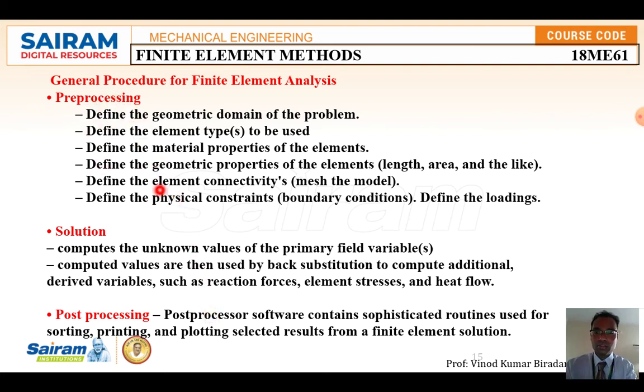All these things we will study. If you solve the numericals in ANSYS, you will understand. Pre-processing is giving the length, area, and all the input data to the system, and according to that it will process. That is called the solution. Once the solution is done, you get post-processing, which is to show the result.